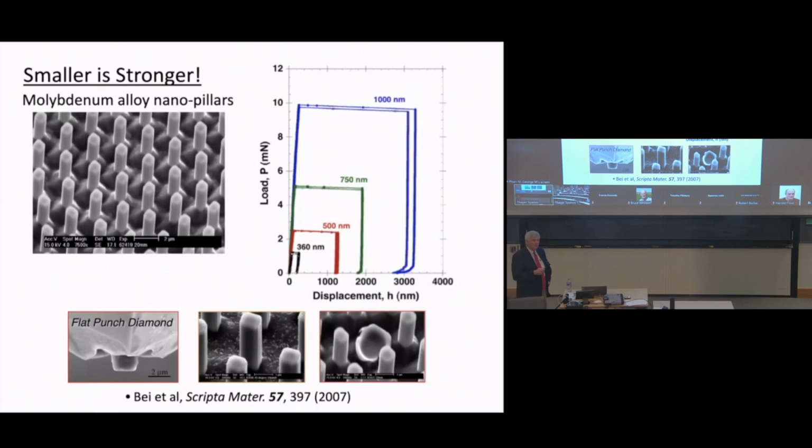And so this is a directionally solidified eutectic of moly. These are nominally moly fibers that grow in a matrix of nickel aluminide. If you directionally solidify these things, the two phases grow in that particular direction.